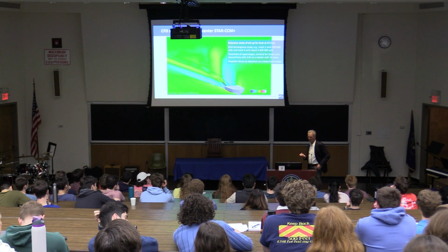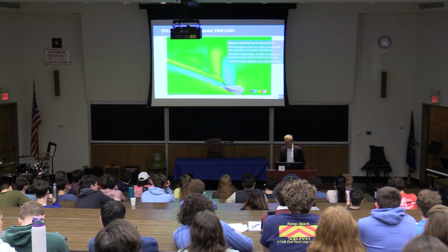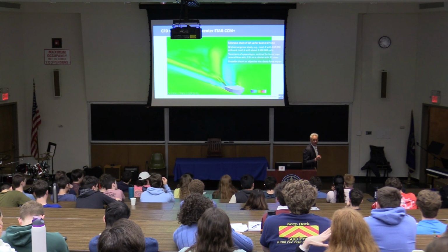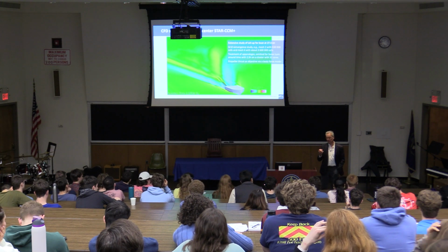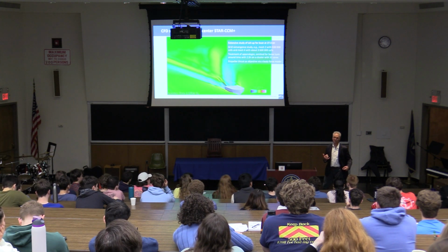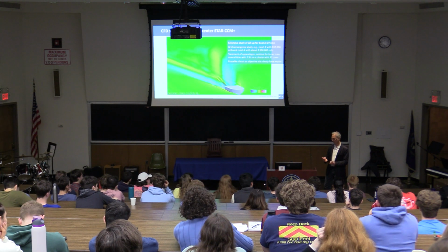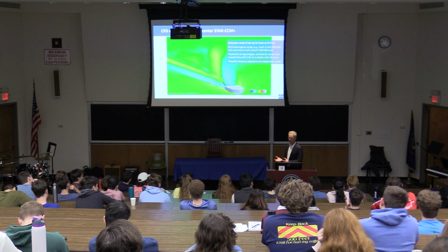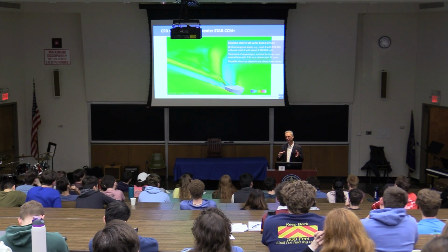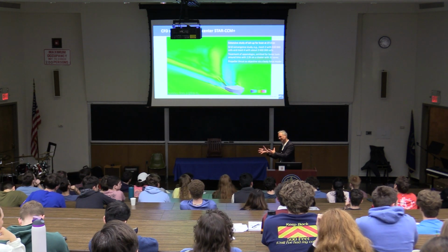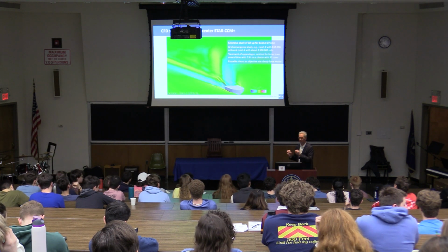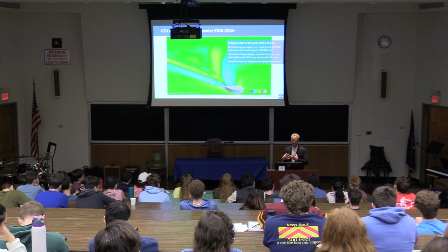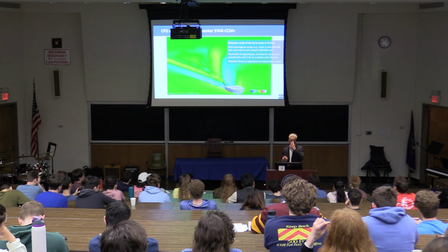Why thrust as an objective? If you take resistance and omit the effect of the propeller, you get a different pressure field in the transom region, and that will change your running attitude, and the running attitude will change your resistance and your trim and everything. So you will not optimize for the actual situation that you hopefully encounter then in real life. So for this particular design, it was important to look at thrust, because then the propeller effect would be captured.